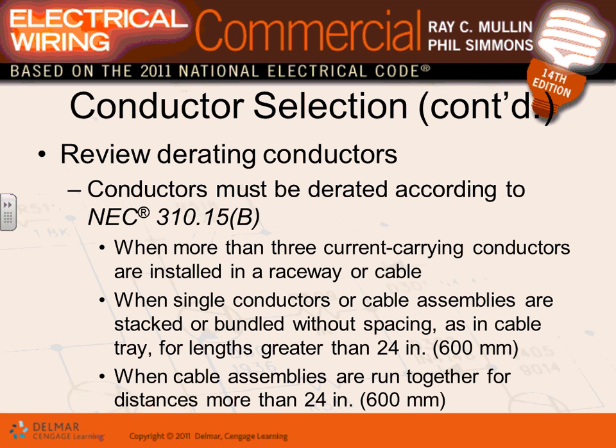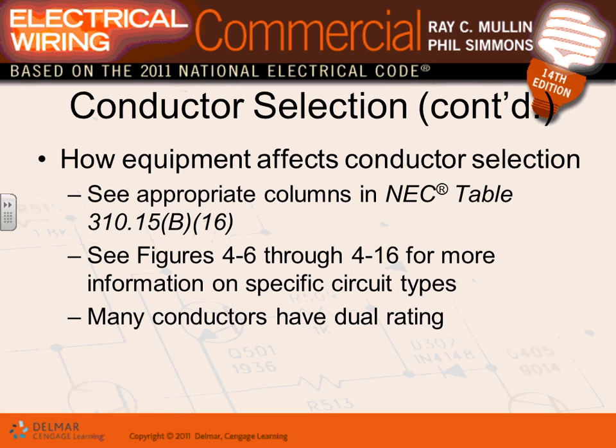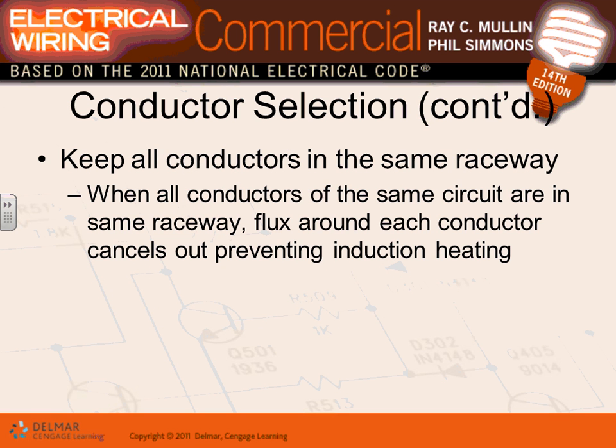So summary, guys. You have to derate for a couple of situations. If you group, you have to derate. If you put them in a conduit more than 24 inches, you have to derate. If you put the cables, a cable assembly, run together more than 24 inches, not separated, you also have to derate. You'll see a picture of that one. Okay, so we'll talk about this figure.